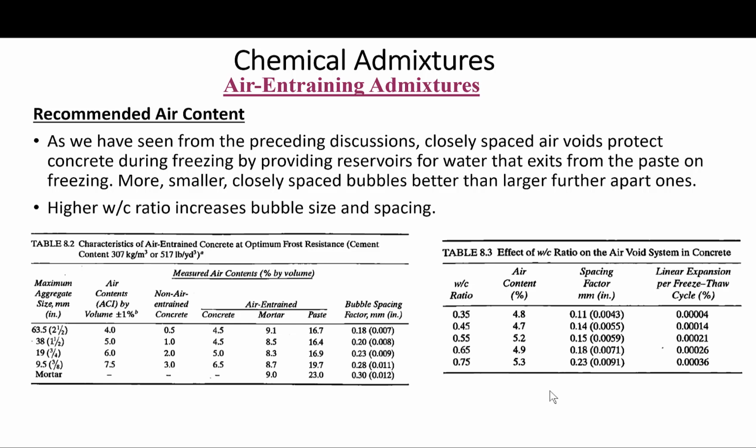So the recommendations in table 8.2 here should therefore be used sensibly. I mean, they should be applied to concretes that will be exposed to severe conditions, where freeze-thaw cycles may be frequent, where ice and salts, for example, will commonly be used, or where sulfate attacks are anticipated.